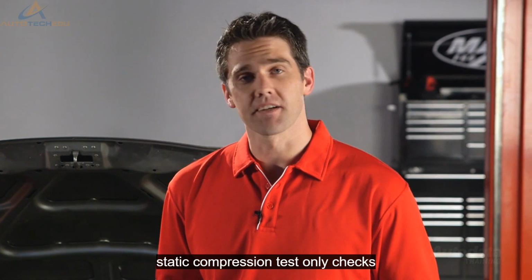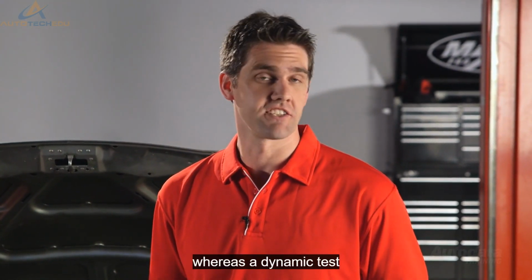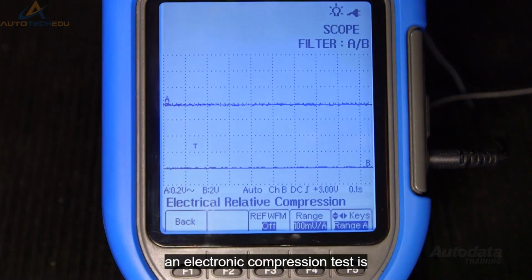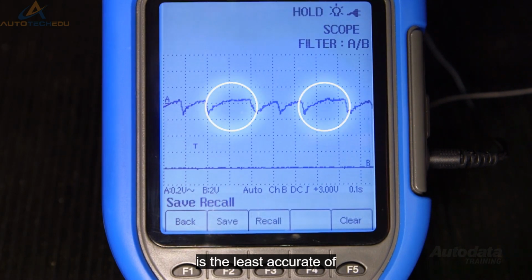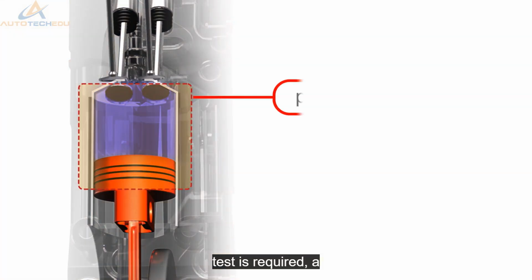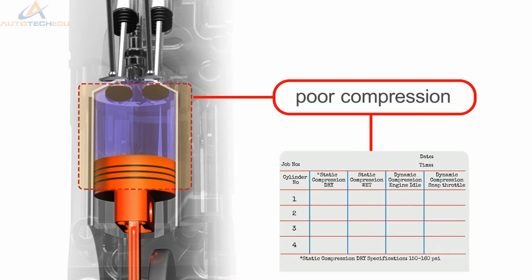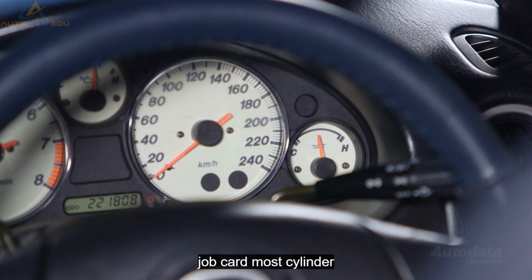This is because a static compression test only checks a cylinder's ability to seal, whereas a dynamic test can isolate airflow problems. An electronic compression test is very easy to perform, but is the least accurate of the 3. Once you have determined that a compression test is required, a compression test analysis form should be used. This form should be attached to the repair order or job card. Most cylinder compression testing should be carried out with the engine at normal operating temperature.